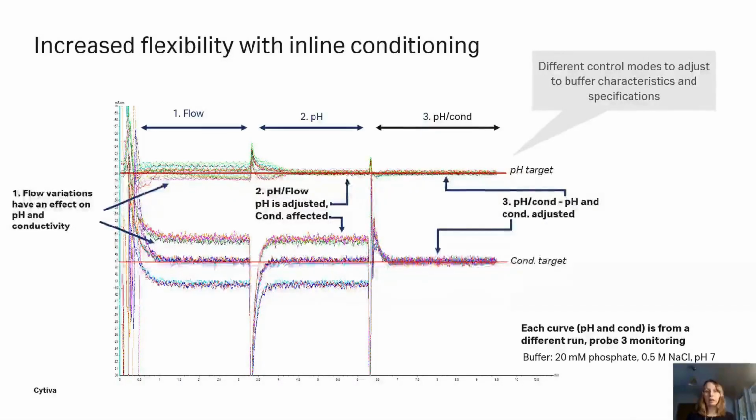The first being flow feedback, where you basically enter a percentage for each pump, which is similar to inline dilution. The next level is adding the pH feedback, and then the third is the pH and conductivity feedback. So what you can see here then on the result is that in the first part of the curve where we used flow feedback, there was no compensation for the errors in the incoming stock solutions. So the data is quite scattered.